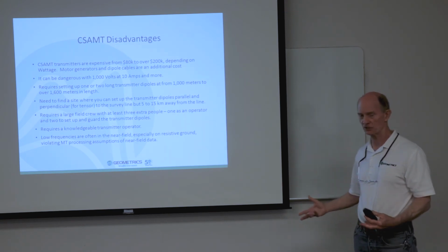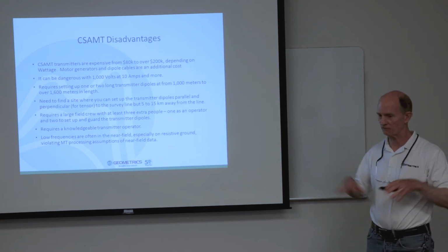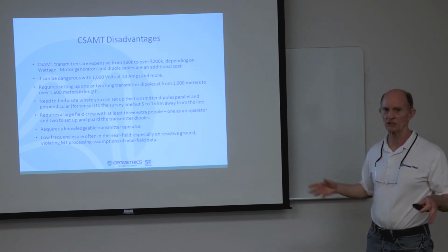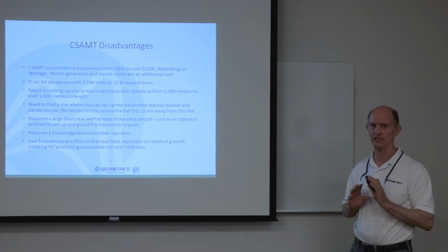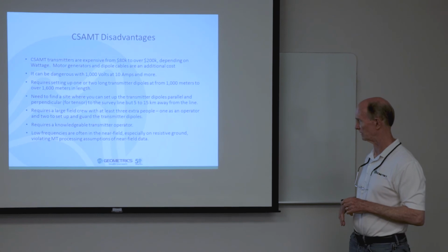And you need to find a site that's 5, 10, 15 kilometers away from your survey area where you can put up these long dipoles parallel to your survey line, and if you're doing a tensor survey, parallel and perpendicular to your survey line.